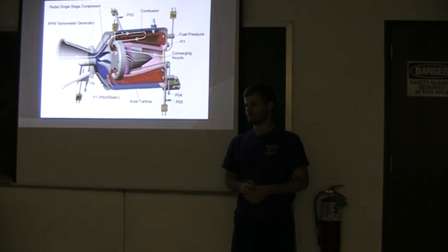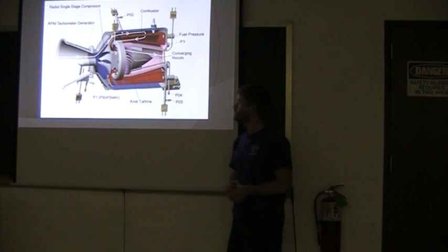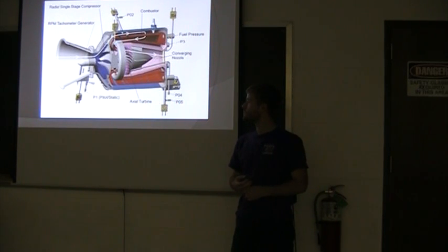And the other question is, you see the configuration over there. You have a compressor, and then after the compressor, you have a combustor, right? In airplane engines, you will see that they have combustor cans. So they don't have just one combustor, but several cans over there. And the function of the combustor, like you mentioned, was just to increase the temperature, right? It's isobaric, but you're providing a lot of energy so that you increase the entropy. And right after the combustor, you have the turbine, and then you have the nozzle. So my question is, do you really require a turbine there, or could you have just done with the nozzle?